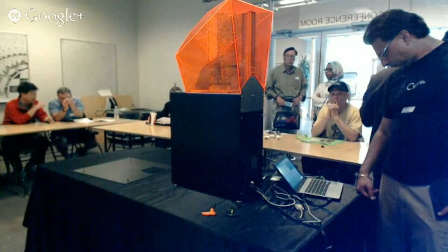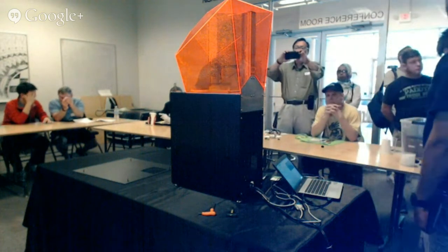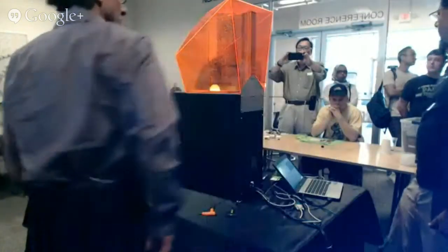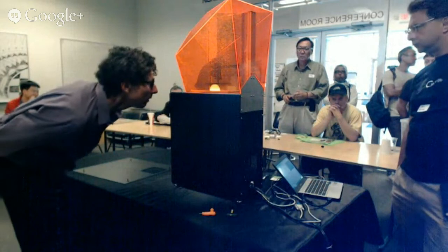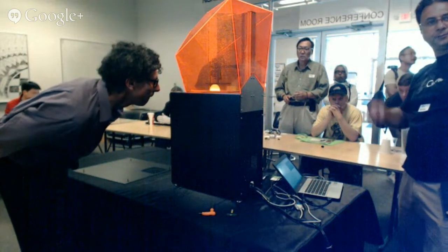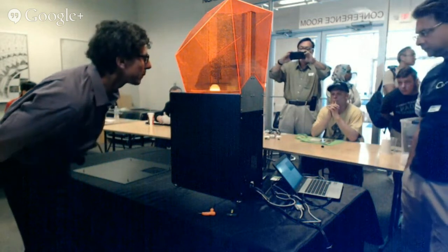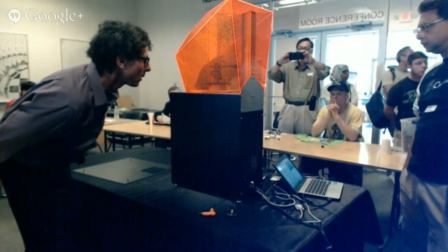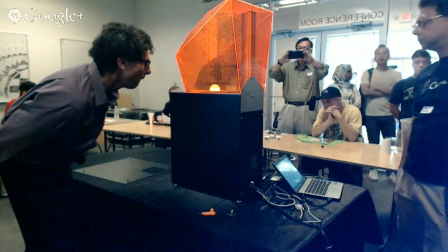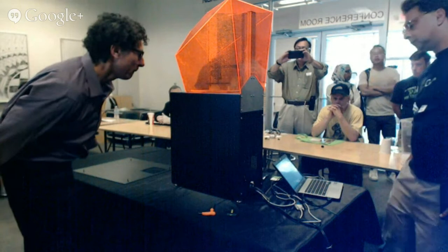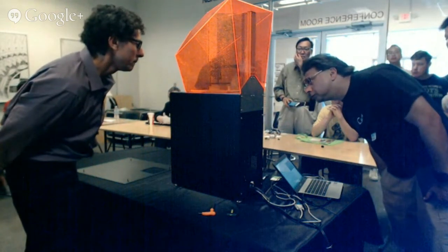Because sticking is a vacuum, right? And so we do better with releasing the vacuum by getting some shear in, with the flexing of the vat, rather than trying to pull it straight off the top. The flexing of this vat helps get some shear in so that you're sliding it. Vat. Oh, vat. Right. And that's why this vat is flexing as it lifts, and that helps release the part.